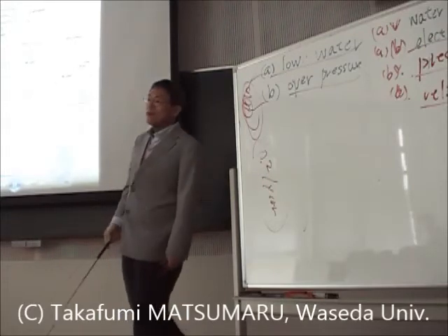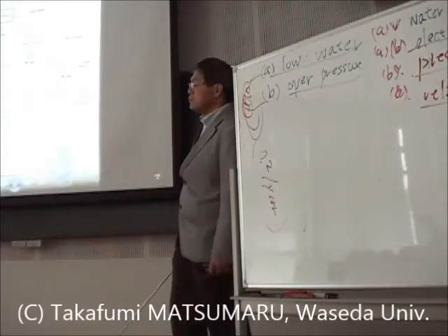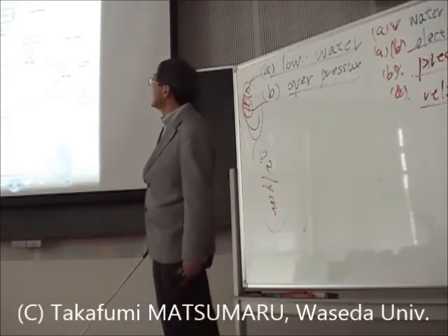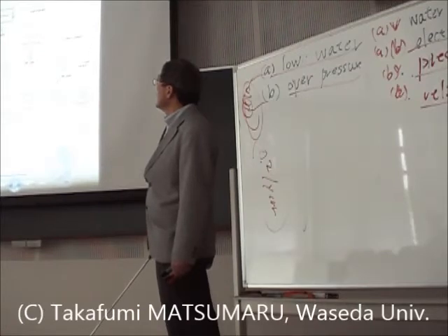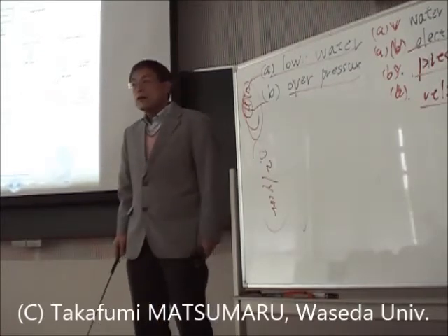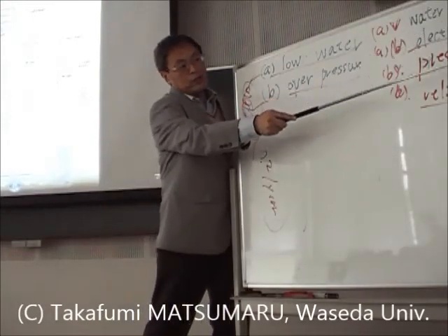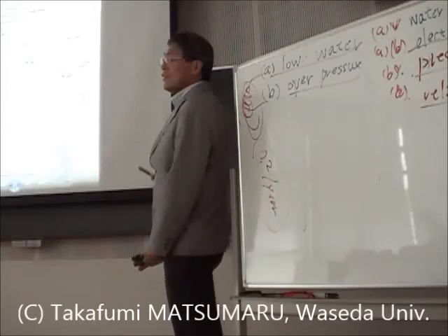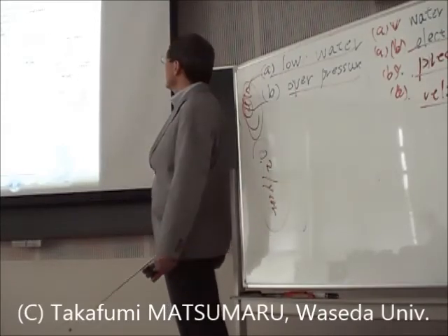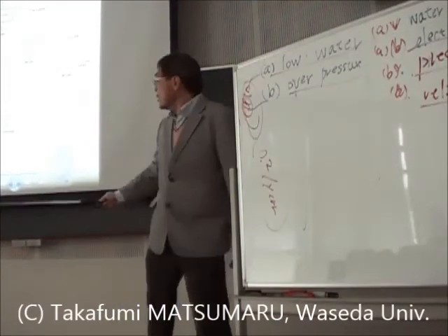I think that the main thing to remember here is to make sure that you have the operator exposed in the top, the first level event. Okay, what we need to do now is apply the frequencies from the table. So for condition A, the failure, well, possibility, the frequency for the level detector is 0.1 per year. The frequency for the electrical fault 0.15 per year.